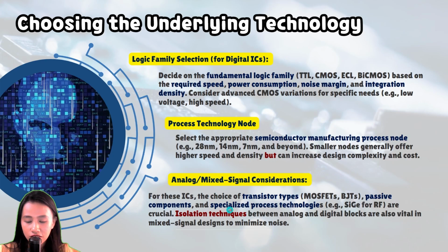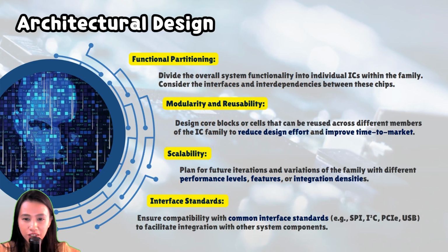Analog mixed signal considerations natin, we also have the transistor types, just in case, yung mga components natin. And of course, we also have yung specialized process technologies natin. Kasi nga mixed siya, you also have to make sure na yung isolation techniques between the analog block natin and yung digital block natin will not disturb each other. Yun na lang yung word na gagamitin ko. Disturb each other.